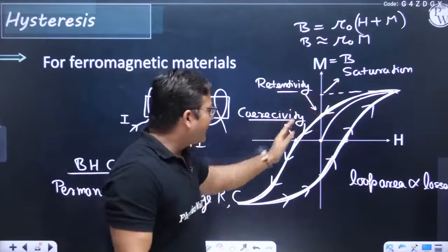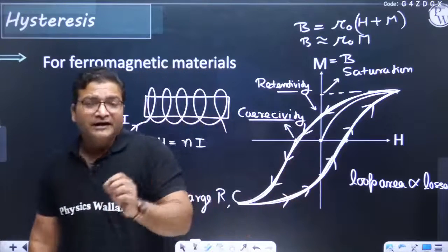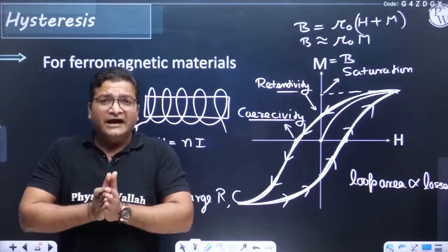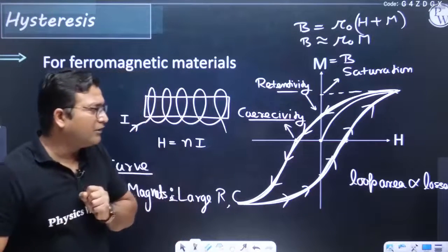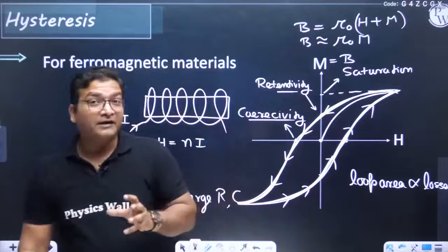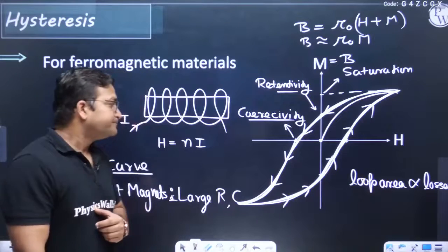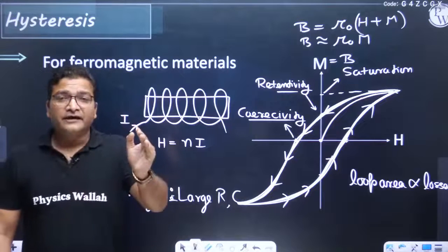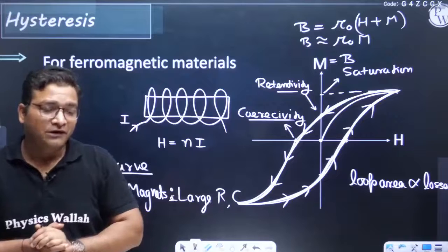When we keep on magnetizing and demagnetizing, the magnetic substance is repeatedly magnetized and demagnetized, and that creates a lot of heat losses, proportional to the loop area. So bigger is the area, bigger are the loop losses, also called hysteresis losses. In case of permanent magnets, we magnetize it once and then the external effects are removed, so we are not much worried about the losses.